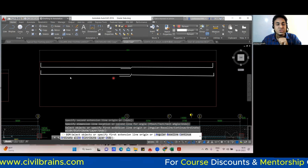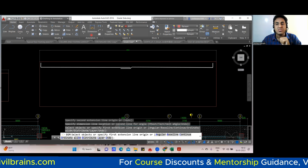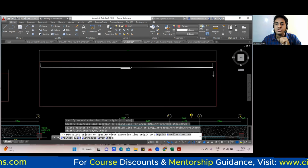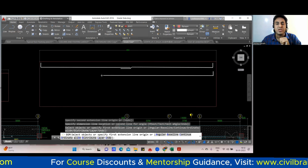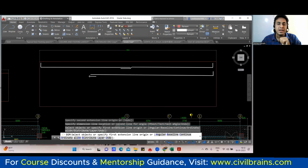So what we'll do, the next bar will not put like this. Next bar, what I'll do, I'll change it. Change in the sense, I'll start to put the bar from here. And I'll take a straight 12 meter bar, which may end somewhere here. Fine. The moment the 12 meter bar ends here, I'll bring one more bar. Then I'll do the lapping.